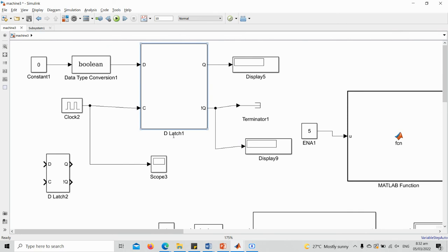You can actually rename it. We have two inputs, the data and the clock, and we have the output Q and the output Q naught. In your logic circuit design, that's why I'm asking whether you fully understand that. I think I have a module there explaining the D flip-flop. Basically, the Q here is similar to the input. Whatever input it is, that will be the output in Q. But for the Q naught, it's simply the inverse of the D. But since it is a D flip-flop, state is very important, so we make use of the clock.